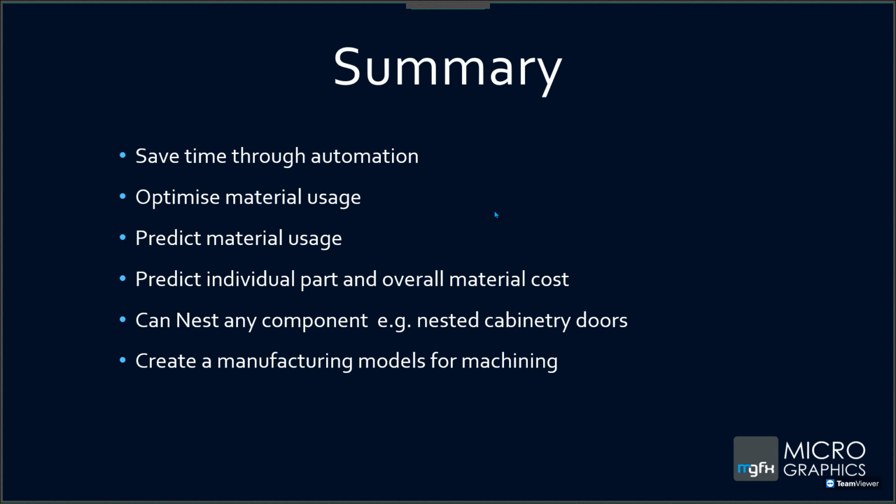Yeah, so to summarize, why would you want to do nesting? It will save time through automation. Like I said, playing Tetris. It's going to save that time. It's going to optimize your material usage within your process, and it will allow you to predict material usage as well for ordering. You know, you have a job coming up, you can do the nesting, and you know, okay, I need to order 10 sheets of that material. And it'll also allow you to predict individual part and overall material costs. That will help with your cash flow. It also helps you to quote the customer.